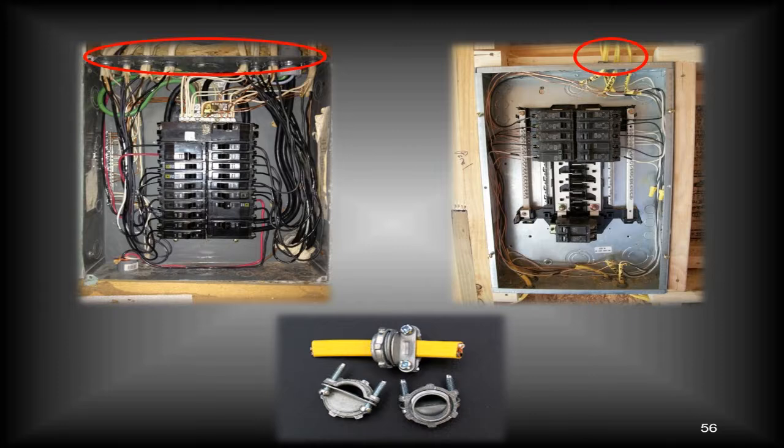Well, one primary reason. Remember, all the way back to the first couple of minutes that we spent in the program here, we talked about two things that always go into the code: protect the people, protect the structure. One of the things we're looking at here is structural integrity. Right now, as it sits in that lower middle picture there, that non-metallic cable is taking up the entire fitting. And if you look at it, you would see, if you could move it all around, there's no light going through there or anything like that.